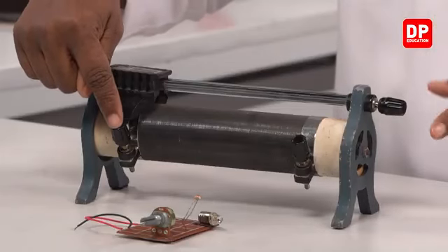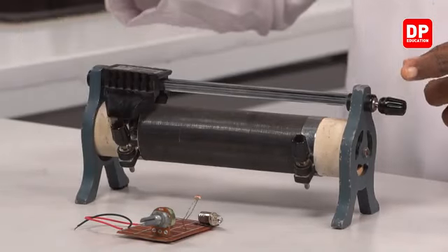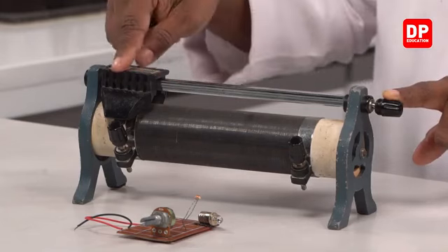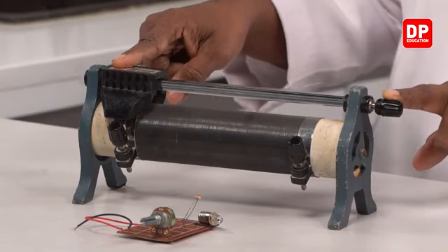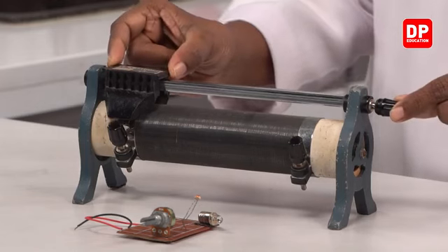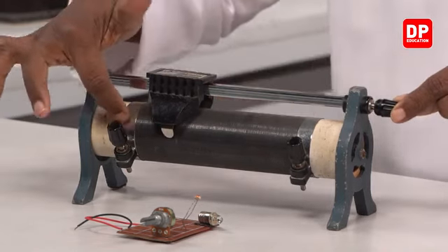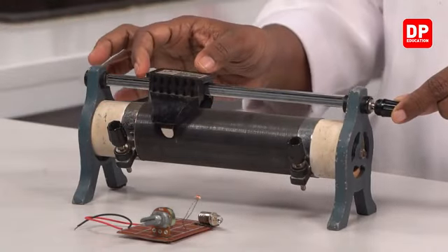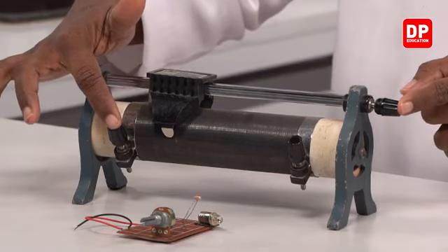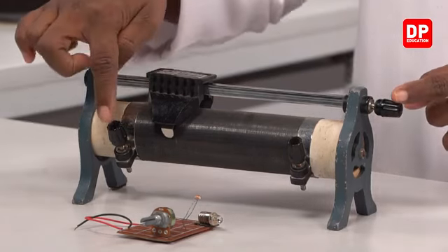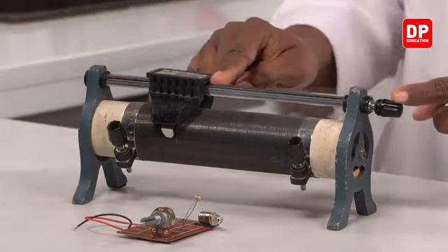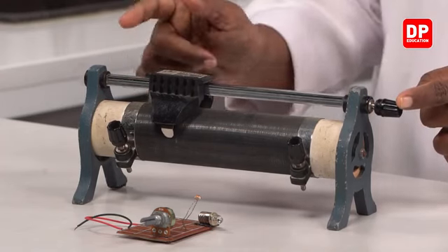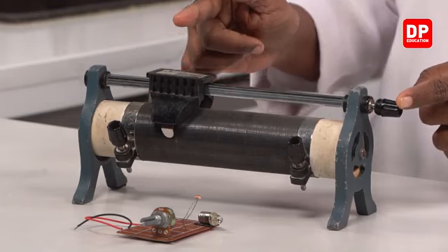If we connect this terminal and this terminal, then when this knob is on this side, it is touching only a very few coils. So that means the resistance is less. But if I move this part somewhere here, now you can see these coils come as the resistor. So the number of coils increases. So we connect the 2 terminals here and here. So the connection is with this, and this metal rod is connected to this knob here. So this part is the resistor. So when the number of coils increases, the resistance increases.